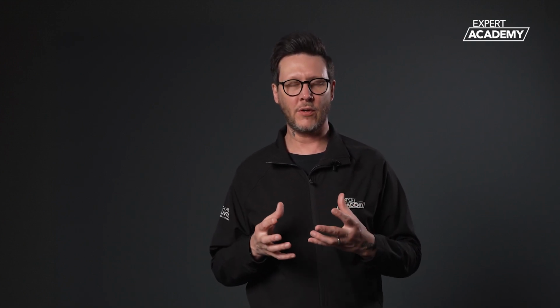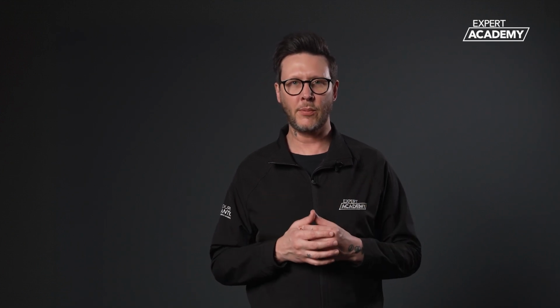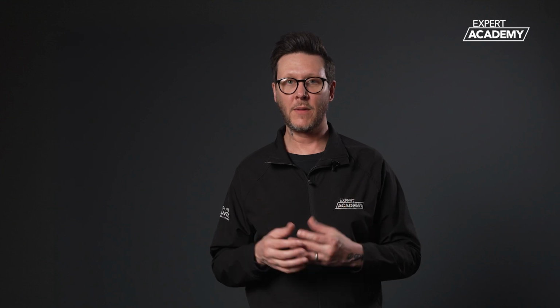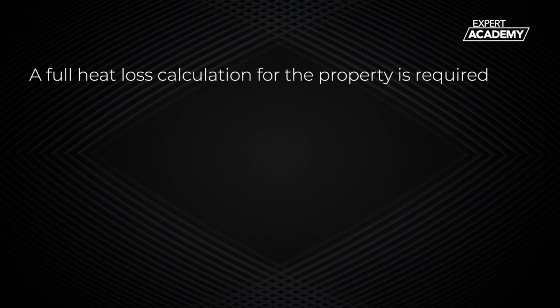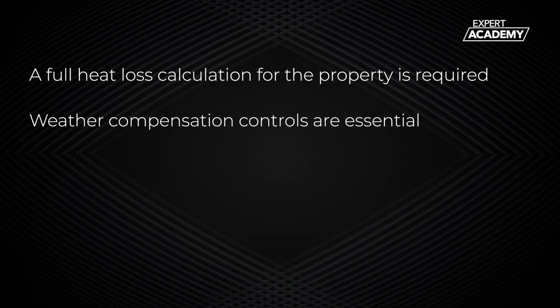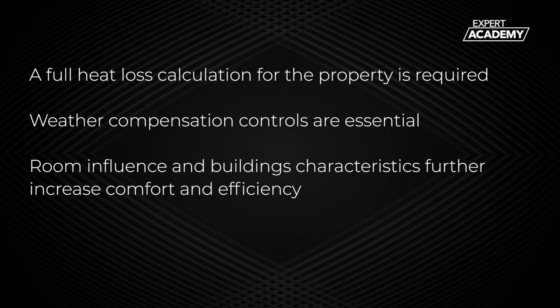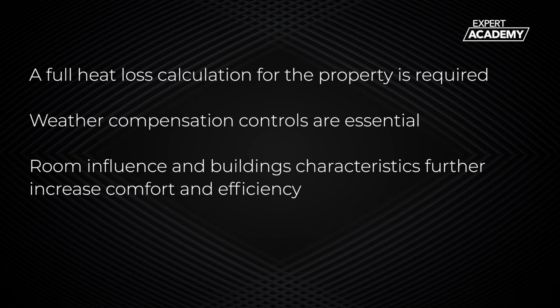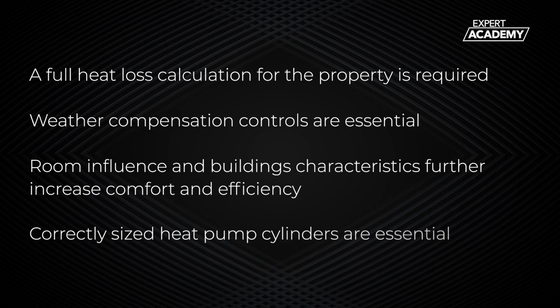We have covered a lot of content to provide a high-level overview of heat pump controls. Controls play a crucial role in a heat pump's performance and efficiency. The main points that we have covered are: a full heat loss calculation for the property is required. Weather compensation controls are essential. Controls that also feature room influence and learn the building's characteristics further increase comfort and efficiency. And correctly sized heat pump cylinders are essential.